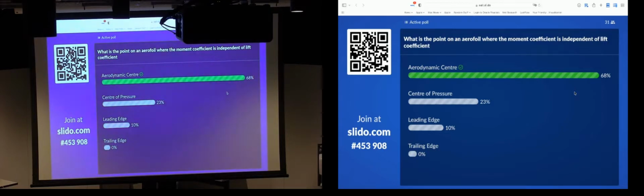So it's nose down, generating 0 lift. To get nose down, if I define lift as positive up, we'll use up in this case, I need it to push up. But of course, it's generating no lift. So where does that have to be located? Yeah. Somewhere infinitely far behind the airfoil. As in, it's gone all the way around the world and come back again and done it again.